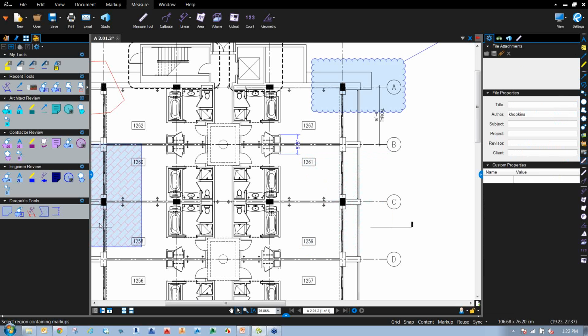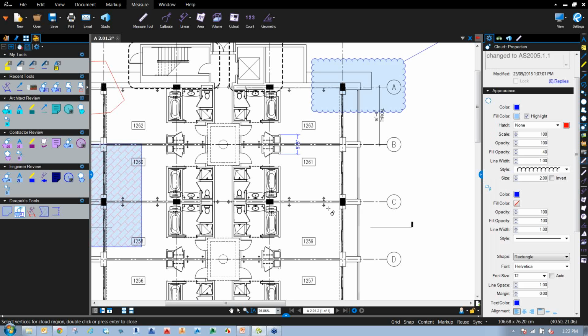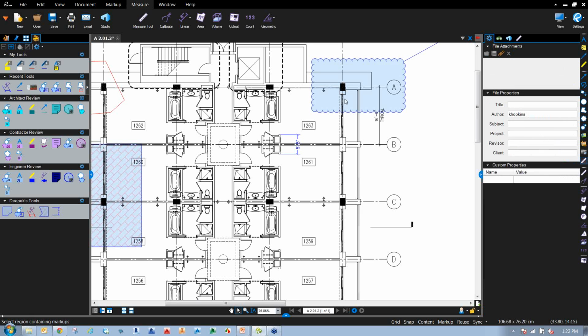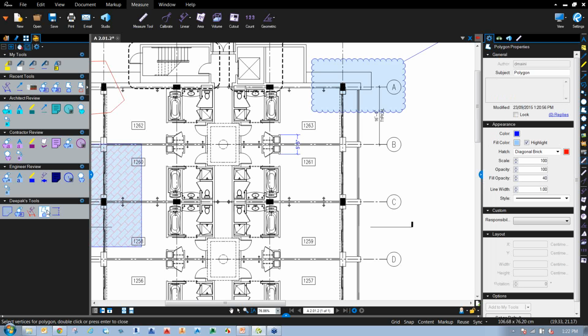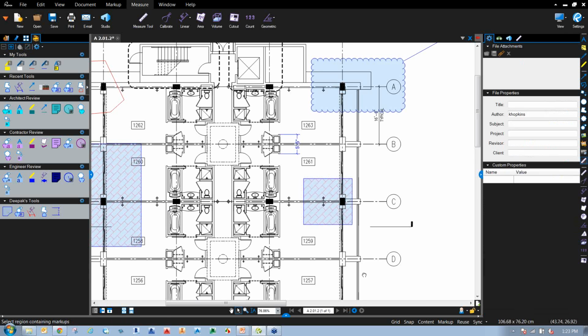Now, I don't want to do that. I want to be able to just pick points wherever I want and then add my own object. So similarly, if I click on this Rev Cloud here, instead of just dragging and dropping, I should be able to resize it as well. So you can double click on any of these command buttons. Once you double click those, it then goes into what we call properties mode. So by going into properties mode, I can actually go and create a new box, but it will have the same properties that we defined for the tools that I saved.